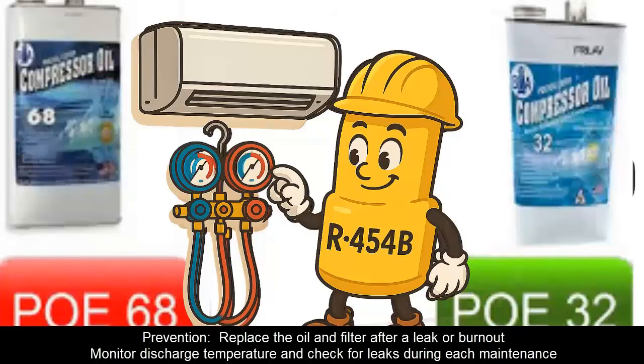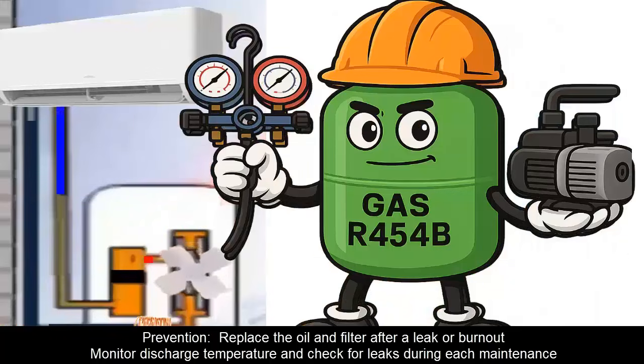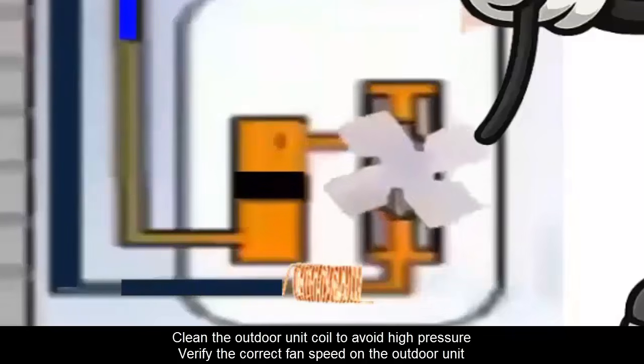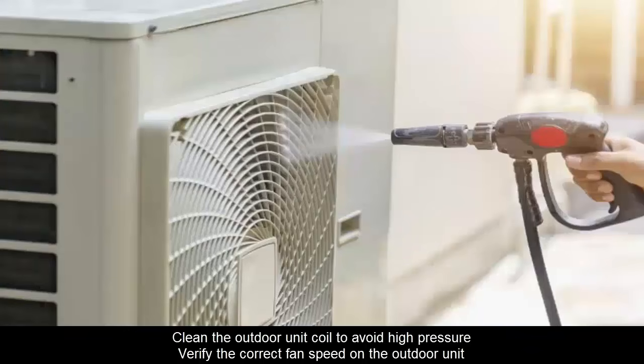Prevention: replace the oil and filter after a leak or burnout. Monitor discharge temperature and check for leaks during each maintenance. Clean the outdoor unit coil to avoid high pressure. Verify the correct fan speed on the outdoor unit.